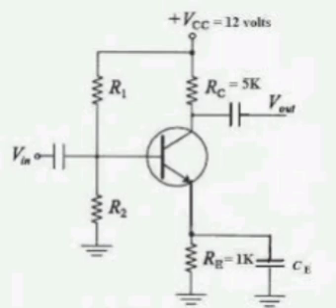Simply you connect a voltage source V. Then V equal to L into di by dt. So everywhere you will get the I by 3 current. Next L by 6 current. V equal to L into d by dt of I by 3 plus L into d by dt of I by 6 plus L into d by dt of I by 3. Solving, V by dI by dt equal to L into 1 by 3 plus 1 by 6 plus 1 by 3. L AB equal to 5 by 6. L equivalent equal to 5 by 6 henries. 5 by 6 henries, option E.